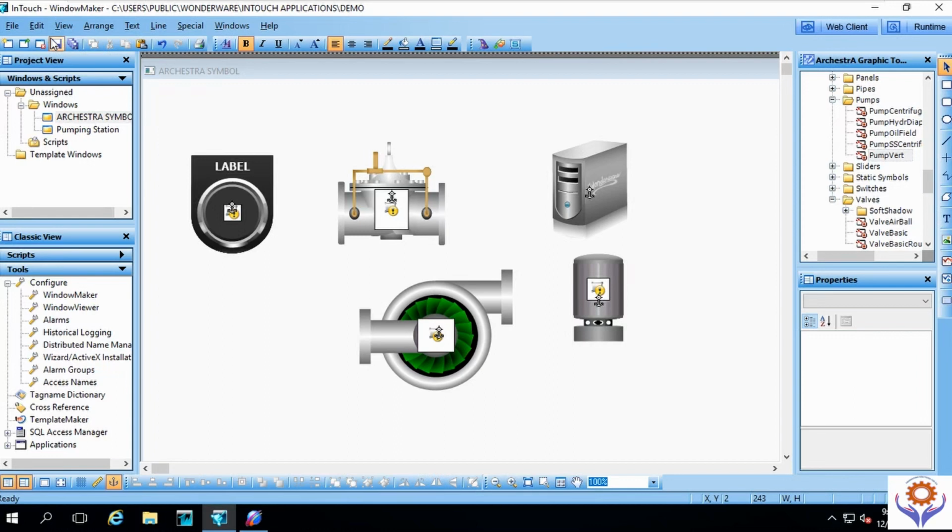So this is the basic part for Intouch SCADA systems. If you need more details, we still need to see the remaining things in part 2, because you have a lot of things you need to create. You need to add the alarm DB loggers, you need to make recipe managers, and you have bind lists to connect with SQL servers, and you have many other details.